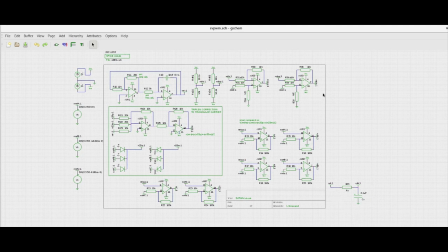These are actually not part of the PWM circuit, because if I have to make a PCB out of it, I need to use only what is inside the page and then put connectors to wherever these items attach. So I have put all these external components for simulation purposes, and what is there inside can be directly sent for making PCB.